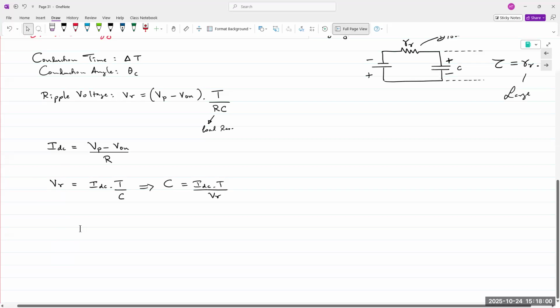Anyway, let's come back. So everybody's done Zener diodes in the lab. If you remember the Zener diode experiment, let's come back to the main point why I brought it up. If you remember the output of the Zener diode, specifically line regulation, you applied a voltage and varied that input voltage, meaning the line voltage coming into the circuit is going up. But even if it goes up, the Zener diode conducts more current through itself and keeps the output voltage constant.